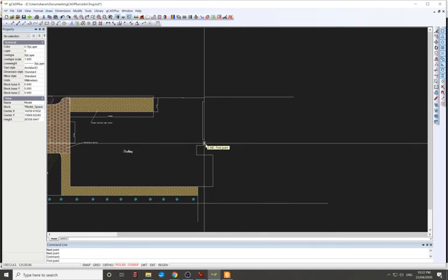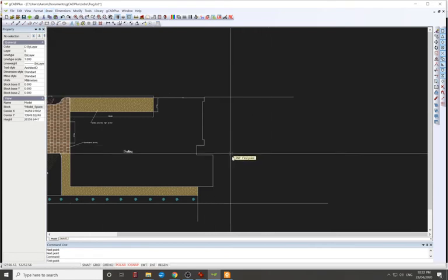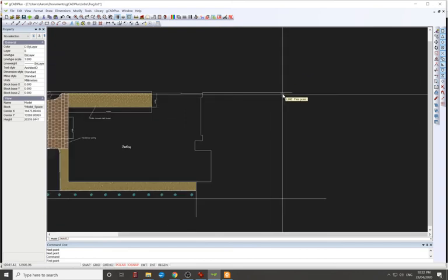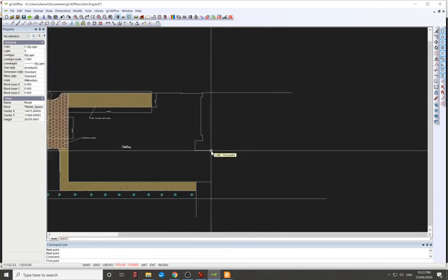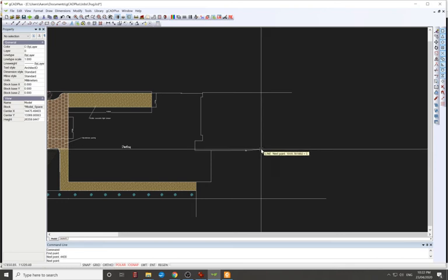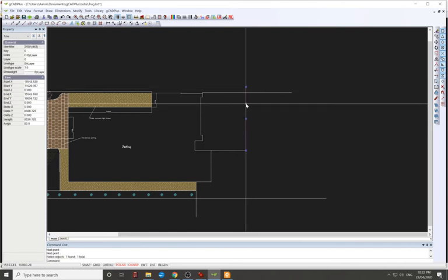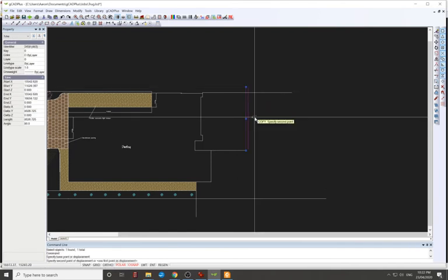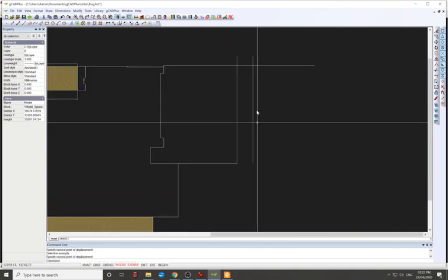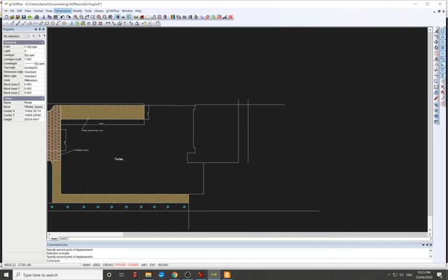So what I'd do here is, to get the frontage of the property, I've measured off this front wall here on the corner and to the front footpath, and it's 4,400. So that's there. So that's the front boundary. And then if you went like this, I don't know how wide the footpath is. I think it's 1,200 to 1,500 wide. And that's your footpath there. And we'll go draw a line here, and that comes out to there.